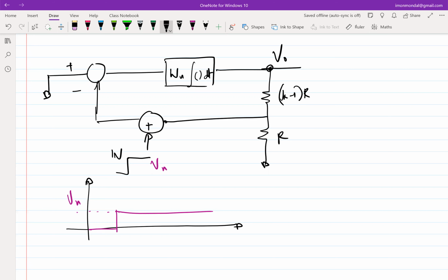It will be a ramp signal. Why? Because this integrator will integrate the small signal, whatever input we are applying here, because this is fed back and gets integrated. Let's do that intuitively. The output starts integrating, so this output starts ramping up or ramping down. Firstly, you have to tell me. It will ramp down, right? This is positive, so this is negative. So this will ramp down. When it ramps down, what happens to the error?